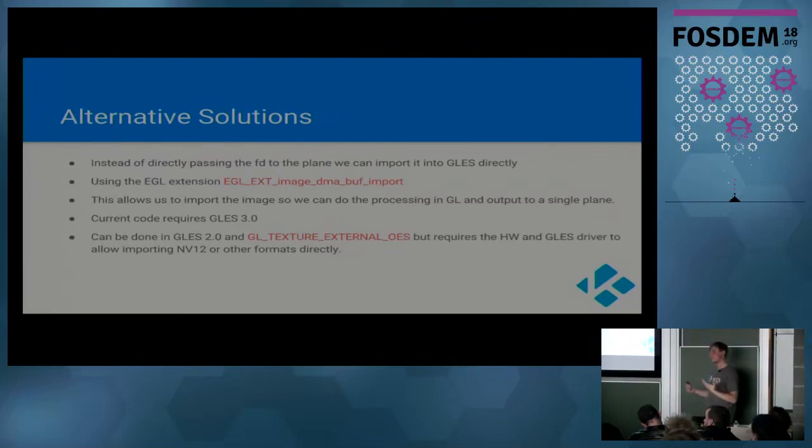Well, I might fix something for you. That would be great. I know IMX6 actually supports outputting YUYV from V4L2, and the plane support and in GL, but I just haven't got around to testing that yet. So no, we will have NV12 support as well.